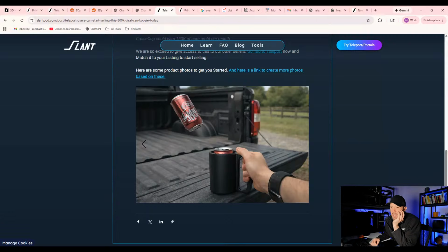Question: how much slop for your internal moving parts would you suggest I use for your printers? I have used 0.3 on either side for moving parts. Adam, I would probably say like 0.2 is about the lowest. Bigger is better. As much slop as you can possibly use and still have a good part, go ahead and use. Like that's the rule.